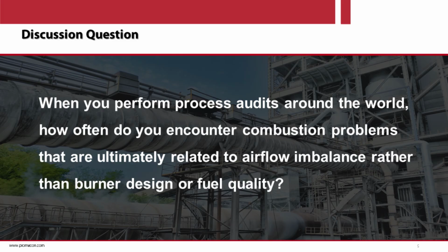So from my perspective, and that is the experience from many plant visits I have done so far, a tilted or unknown air split is one of the major hidden efficiency and performance limiters. And this is happening in quite many cement plants. People are trying to overcome this issue that they cannot see the airflow rates by measuring the kiln inlet oxygen or the preheater exhaust oxygen.